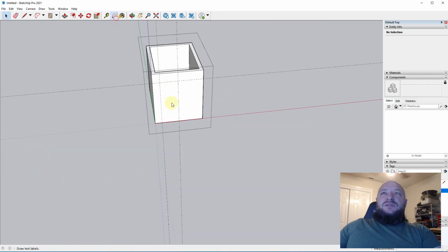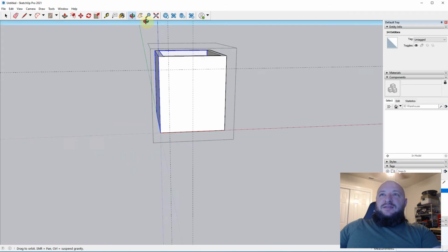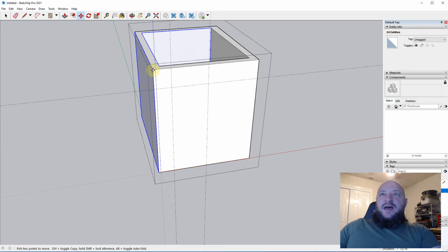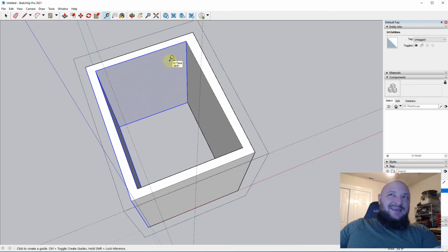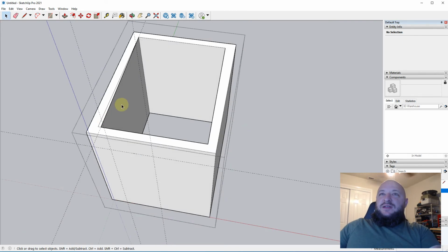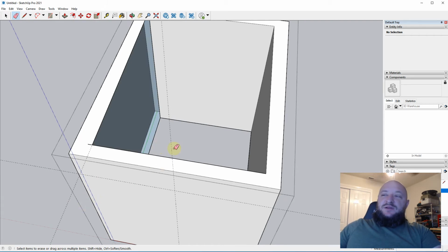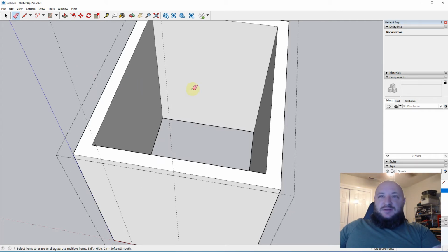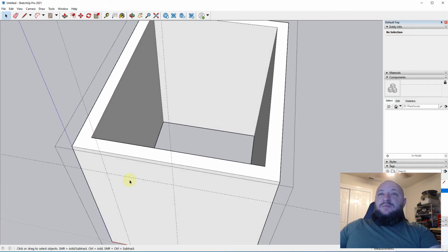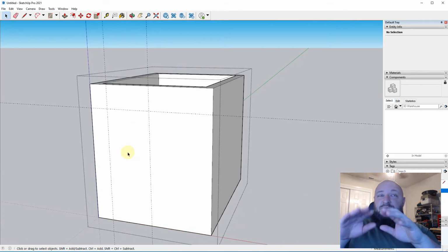Another issue that usually we'll see later on in the semester is someone goes, oh, I want to just move this wall, and so they'll do a selection like that, not see that they got some wall in the back, and then do that, and now you've got a crooked wall right here, but you didn't see it. Then you go to do some other line, come through and trace, and all of a sudden things are filling in funny, and when you go to erase that line, your wall disappears. You've seen that a million times, and it's always because of little weird adjustments like that. So, step back here. Okay, there we go. Always just make sure you're working on one thing. Don't do weird selections in the background, all right?